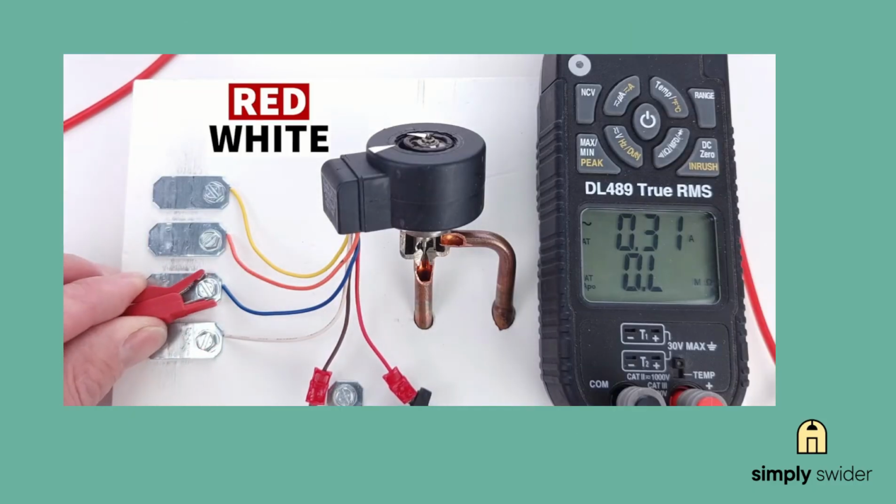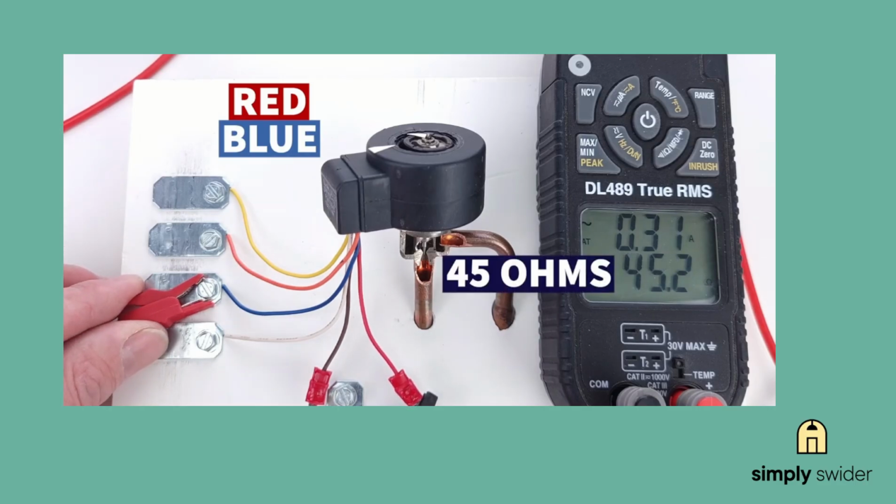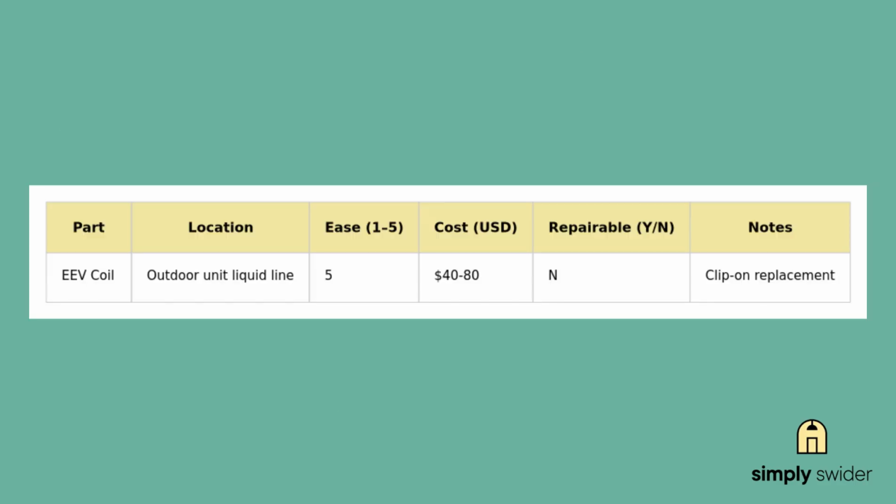If you're comfortable with a multimeter, you can check the coil resistance. We have blue, red, white, and yellow colored wires, usually with a resistance value around 46 ohms between phases. Open or short circuit means the coil's dead.